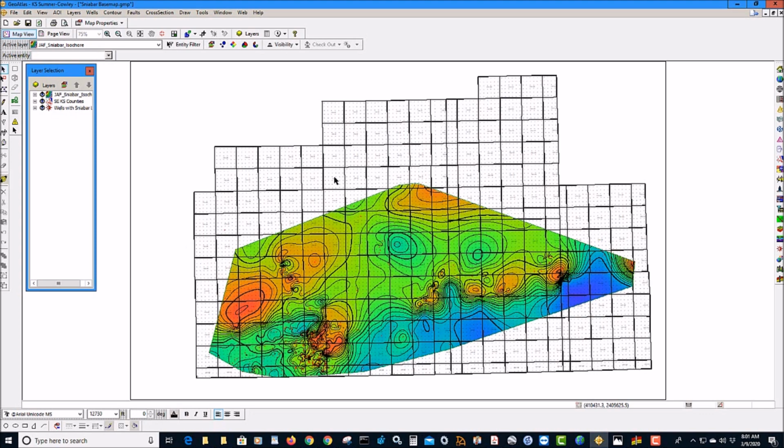All right, I'm going to give you a tip that can save you a lot of heartache, let's say. I've run into a few situations where people have worked for an hour or two on their map and then essentially destroyed their work by updating the layer unnecessarily. So I want to give you this tip. I'm going to copy the contours to a blank IsoMap layer and then underlay the data points with the values underneath the contours on that blank layer. By doing that, I remove the option to update your hand contoured layer, because there's no underlying data or grid, so you can't screw up. That's the bottom line. So let me show you that trick.